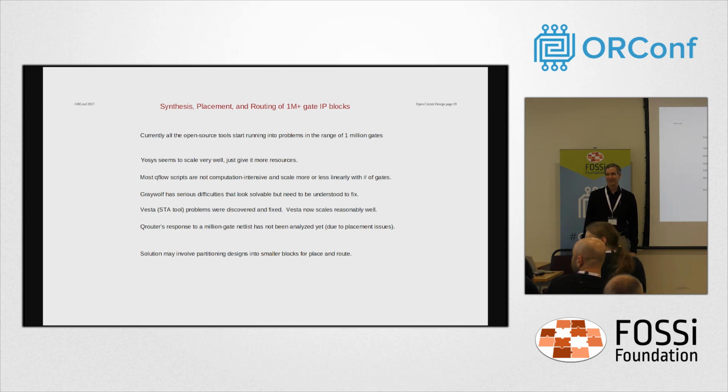Since we just had a talk on formal, I was wondering if in your flow you have an LEC tool, as you told us not to trust the placer and the router, but what about the synthesis tool? Well, the synthesis is all done from Yosys, so I am largely depending on static timing analysis to do all the verification of everything. There are tools to do the verification of that before synthesis, or at least prior to all the back-end things that Qflow is doing. Beyond that, once you have the routed solution, static timing analysis is the best I have for doing that.